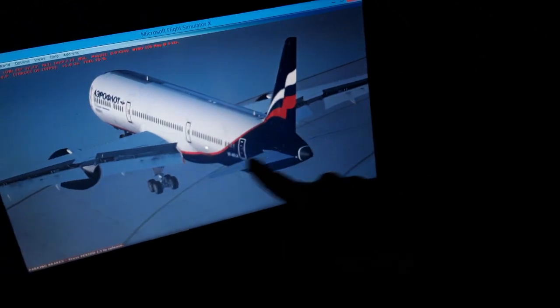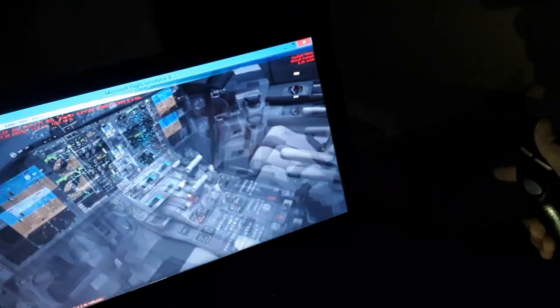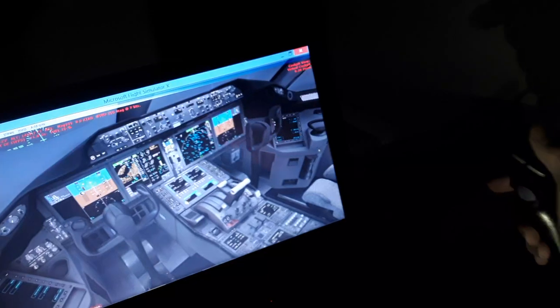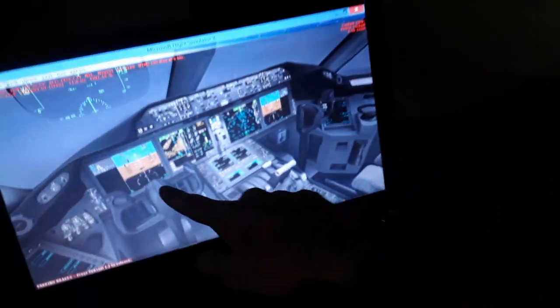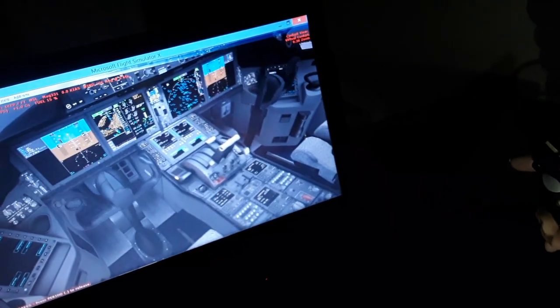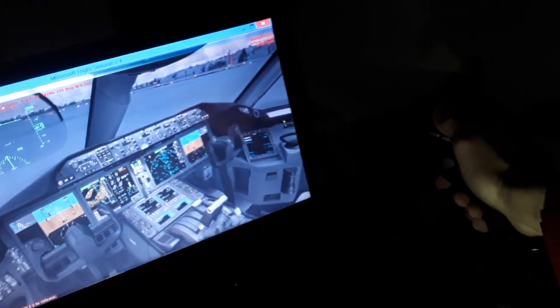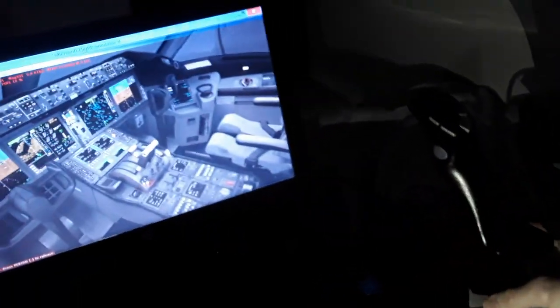Also we have the horizontal elevator trim function that I show you in the trim switch. I have the trim switch here. So we climb and descend, we have the elevator here. It is the yoke, the control column of the Boeing aircraft, the vertical column, for controlling the elevator back and forth, like the side stick back and forth in the Airbus. No difference, same function, same flight control movement.